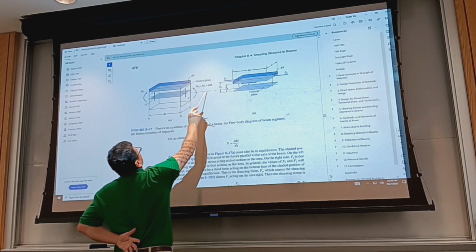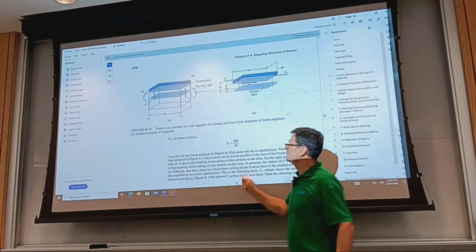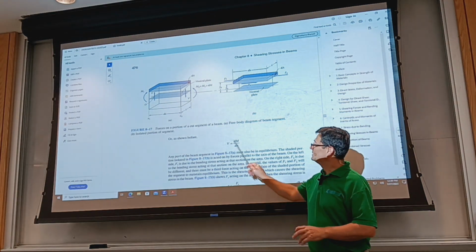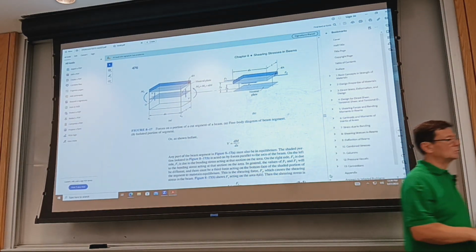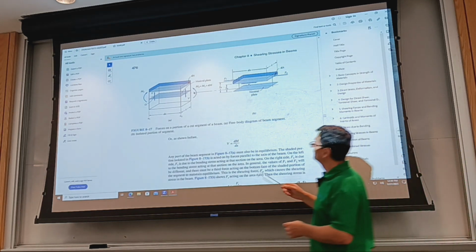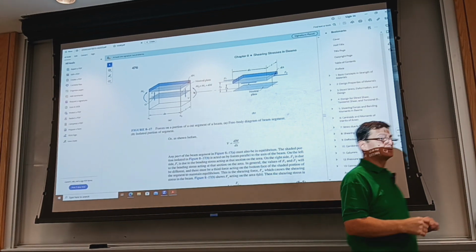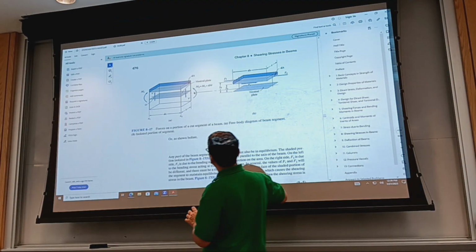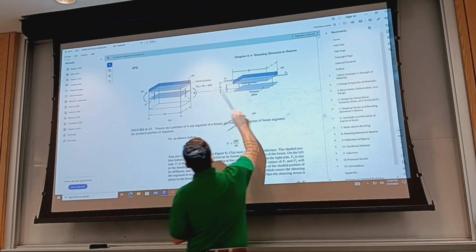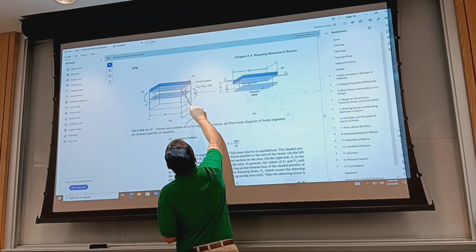So the difference, dM, is taken by this guy. And that's why this formula, dM over dx, is V. This translates into balancing the increase of M by dM due to the shear forces on the vertical surface.